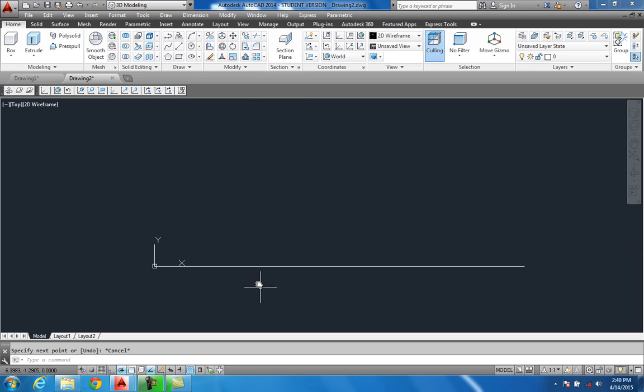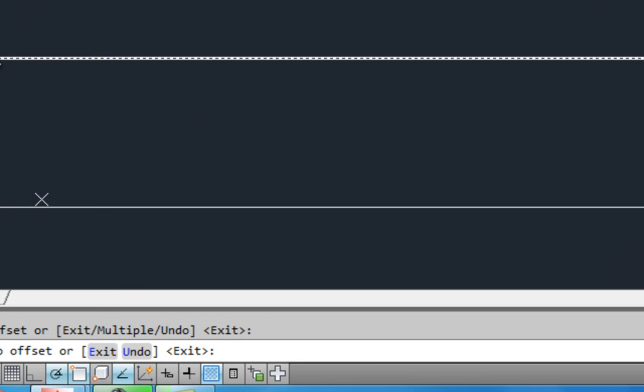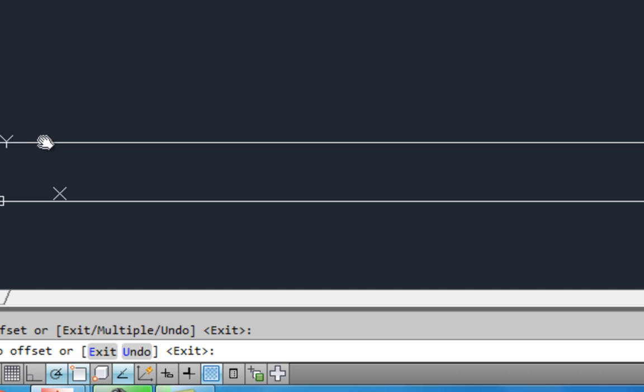Now, let's say for instance I want to draw this round piece, this symmetrical piece, that has a diameter bored through it at 1/2 of an inch. So what you've got to do is offset. If you want a 1/2 inch diameter, you have to do half of that, which would be 1/4 inch. We'll zoom in there and take off from that point. So this right here is 1/2 of an inch. When this part revolves around this axis, it'll be 1/2 of an inch.